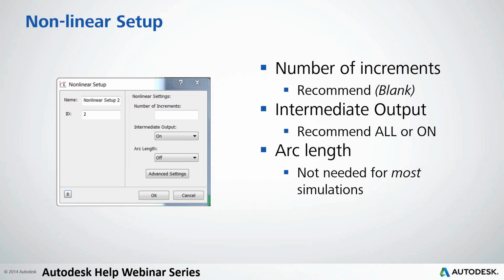But one great trick you can do here is you can actually leave that blank. What it does by leaving that blank is it allows it to auto increment. So it's going to start off at a very, very small increment size, and it's going to incrementally increase that size. You'll start off with an increment of 1, and then it may increase that to 7, and then to 15, and then you'll be going in increments of 30 at the end. So it allows you, at the start of your nonlinear analysis, to hopefully initialize some contact and things like that, and then ramp up the analysis over the course there.